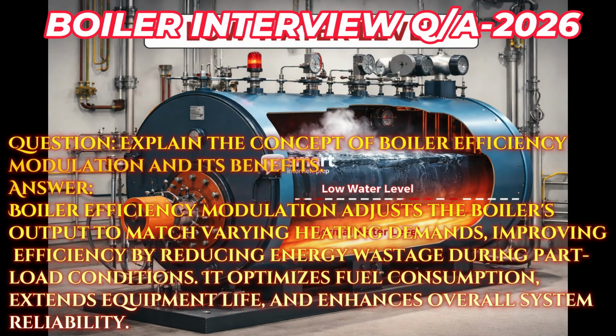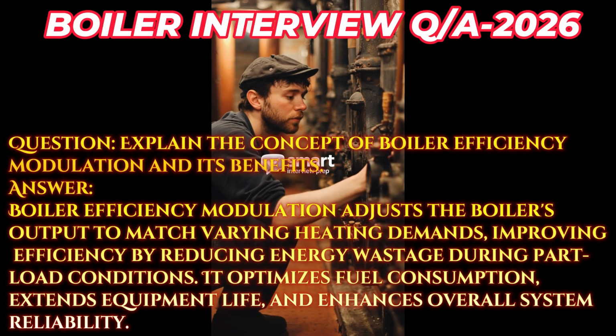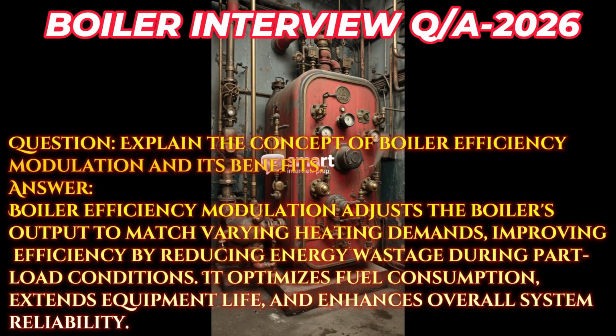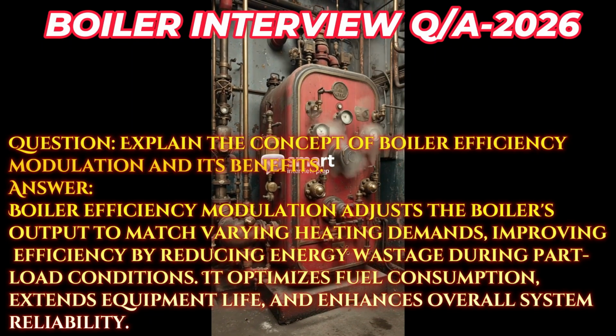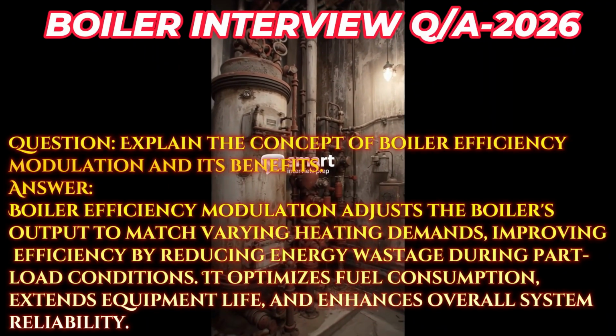Question: explain the concept of boiler efficiency modulation and its benefits. Answer: boiler efficiency modulation adjusts the boiler's output to match varying heating demands, improving efficiency by reducing energy wastage during part load conditions. It optimizes fuel consumption, extends equipment life, and enhances overall system reliability.